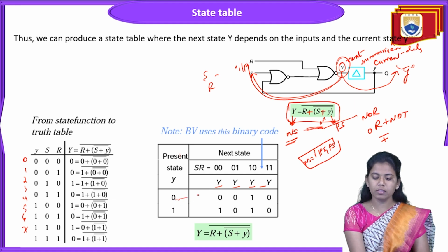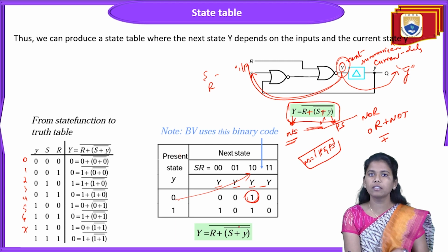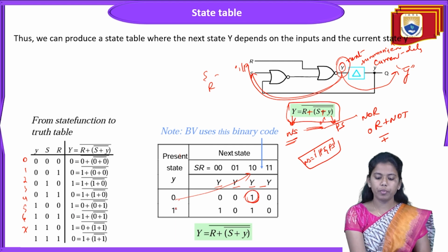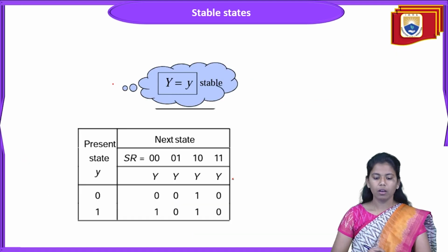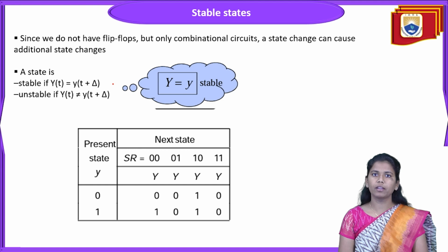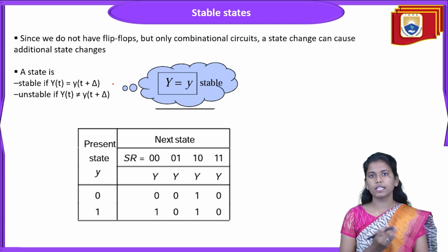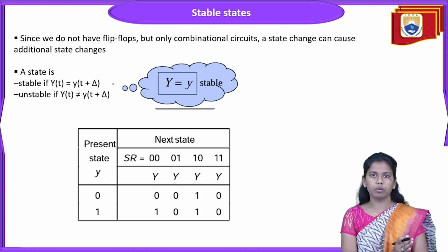Where I can map is at the 1, 0 position, where the state is getting transitioned. Then at present state 1, I can see the combinations at 0, 0 and also at 1, 0. Using the K-map or this particular table, we can easily draw the Karnaugh maps. The Karnaugh maps can be drawn with respect to the truth table or a state table.